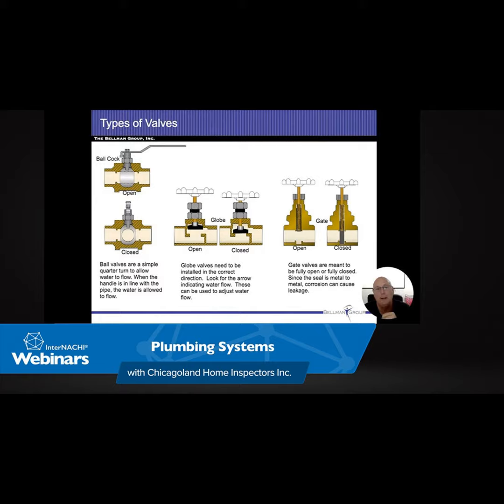So what we do is we have air, or in this case, a piston, a seal in a chamber. Since air is compressible and water is not, as long as I have a chamber of air, compression is going to cushion that stop, and that'll prevent the water hammering. If you turn valves on and off and all of a sudden you hear some rattling, chances are if we have a mechanical device like this, it's broken. If we have an air device, such as the one on the right, those get filled up with water. So the air does get absorbed into the water over time. It's normal. It does happen.